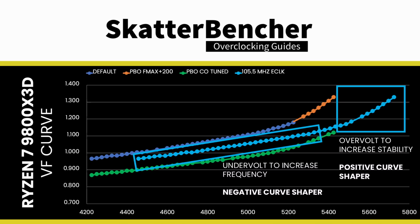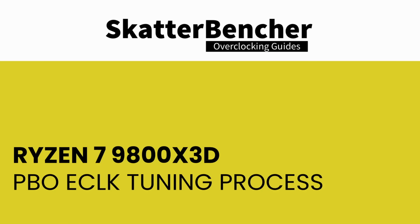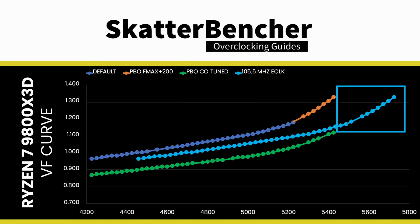Let's get a bit more practical with the process. Similar to Curve Optimizer, the tuning process with eCLK and Curve Shaper can become quite convoluted because we're still talking about that wide range of workloads, from light single-threaded workloads all the way to heavy all-core workloads. My first goal was to find the maximum stable frequency at the upper end of the curve.